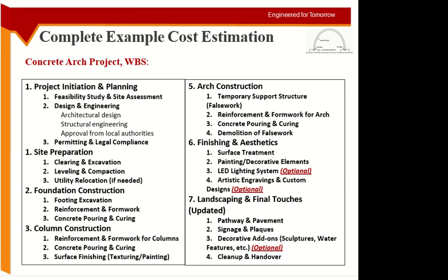So the project starts with initiation and planning. You do the feasibility study of the site, assessment of the site, how is the weather condition, how much space you have, and these type of things. Then you go for the design. The design will be architectural design, structural design, and then the design must be approved from the local authorities. And here you can see initiation and planning are merged, so that's why the approval is at the same stage.